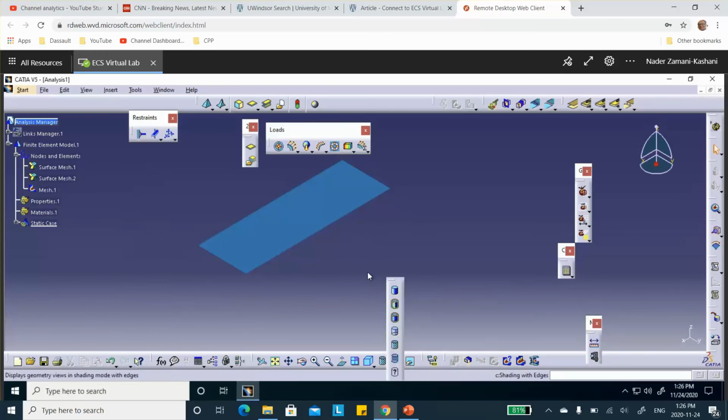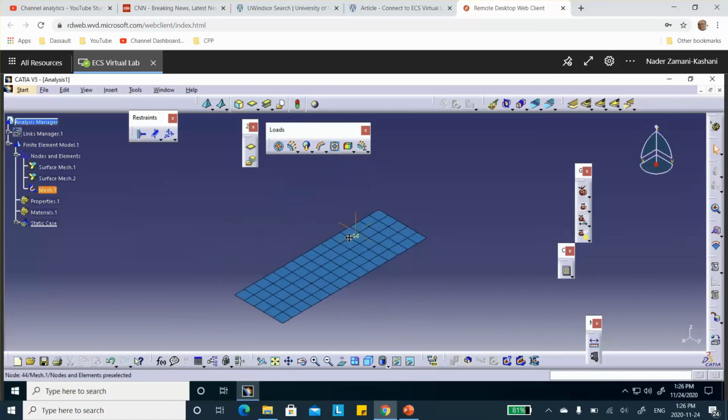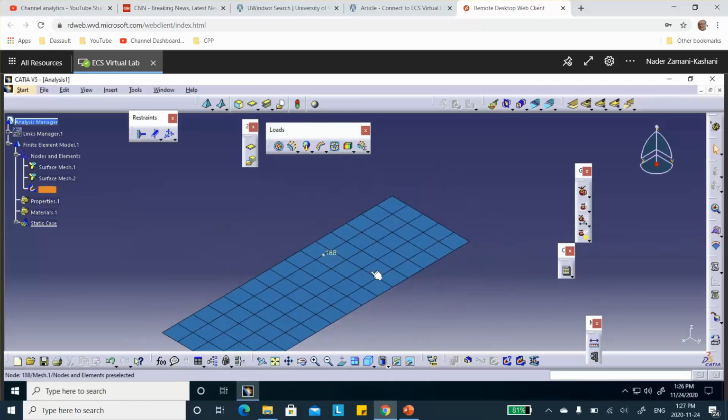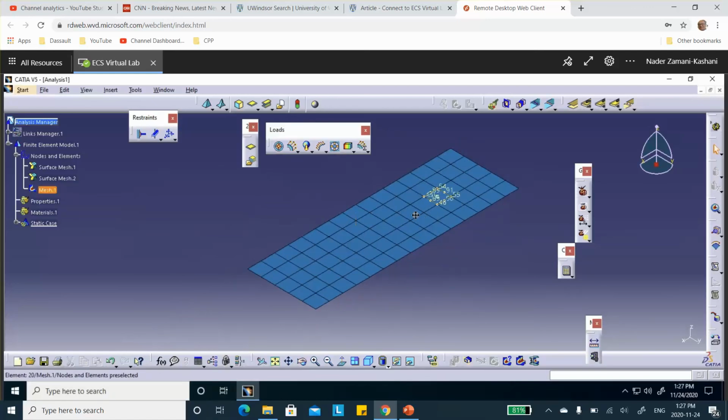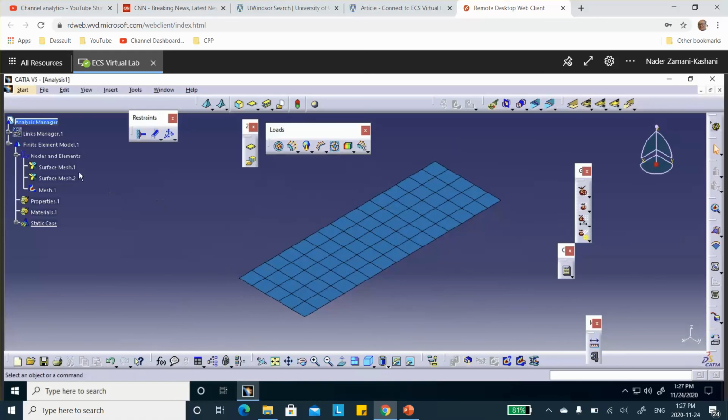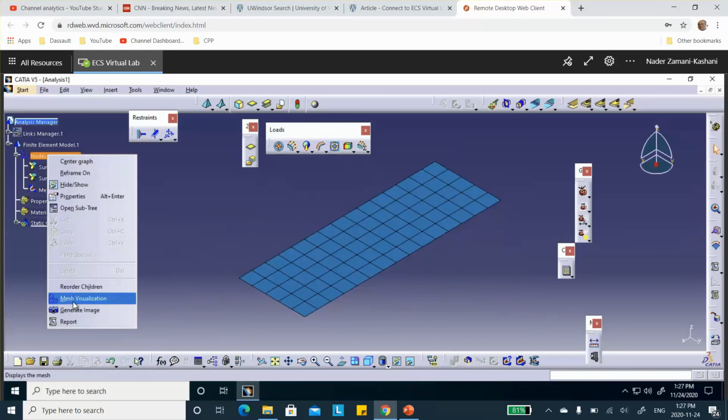Third one. So if you zoom in, you see that that line was here, and if you look at elements on both sides, they have the same node numbers. If I had not merged those nodes, there would have been different numbers on the two sides, and these nodes are not talking to each other unless you create some kind of constraint between them, and the software is going to fall apart, or the run is not going to be successful. We'll see that. I'll do that for you later on. So we deactivate.